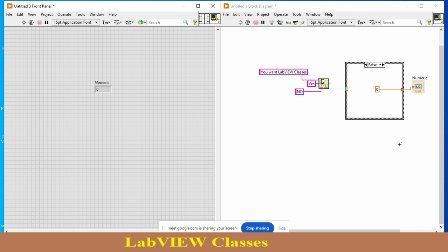It is up to you how to use your LabVIEW symbols or how to use these nodes differently. Right now I am just using a simple constant inside this. You can just put a code also inside this. Like if you want to place the input temperature in Fahrenheit, you just put Fahrenheit code inside it.